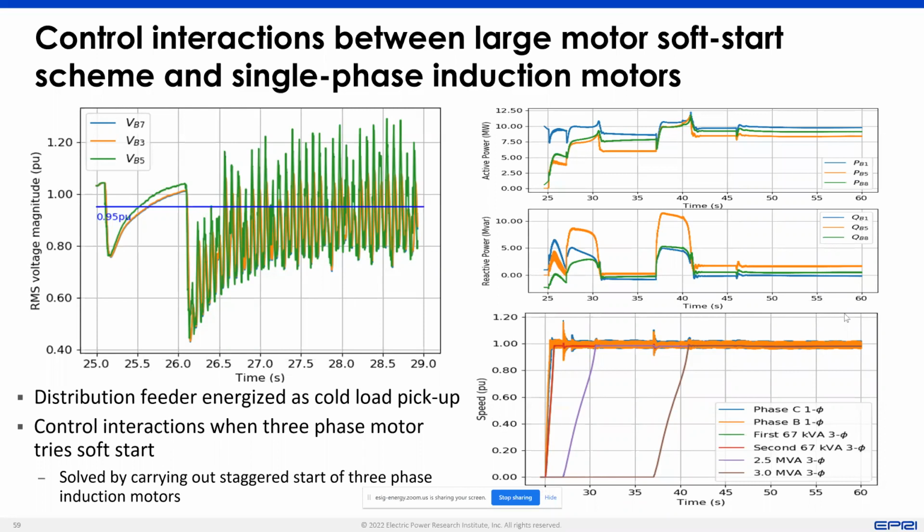So from a steady state perspective, there can be a steady state operating point which can have a successful black start operation. But when you dig down into the real transient operation that can occur in this kind of black start process, you can have these different kinds of interactions come up, which is important to consider when you're looking at black start from an inverter-based resource perspective.